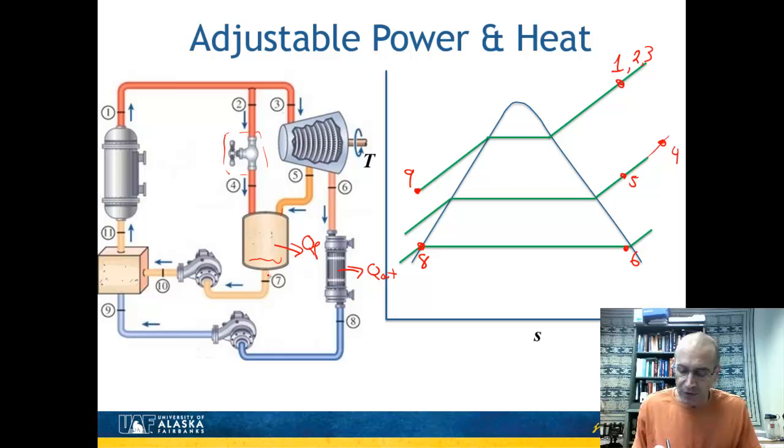We got point 5 labeled. Let's look at the outlet of the process heater, which would be point 7. If this is going to go into the pump, it's going to hopefully be a liquid. So we'll go ahead and have point 7 there. We go through from the middle pressure to the high pressure, point 10. That's an isentropic pump. Point 10 will be right above it. And we're almost done here.